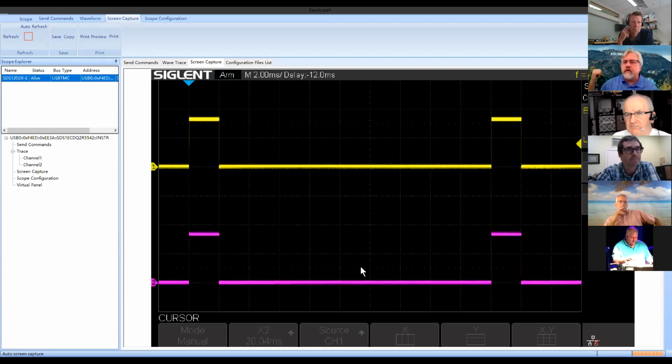There's an assembly cog running too." The smart pins handle the UART data going in and out, but they only have a 1 byte buffer for each. So all the background does is say, "Hey, do you have a byte for me? Yes, you do. I'm going to stick it into the user's buffer." Or, "Hey, the user wants to transmit something. Let me put it into the transmit pin." So it's just a UART manager.